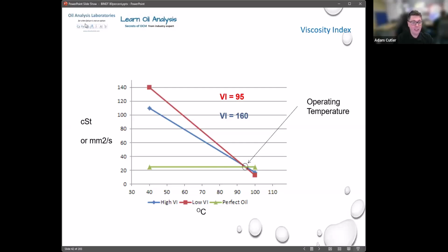But if we're coming into colder months now, as we're getting to freezing or below, it gets thicker and thicker and it's going off screen in terms of viscosity. So that'll take a lot of energy to start up in the morning, or it's very, very thick and gooey. Or you can have an oil that just doesn't go as thin as fast. So rather than having the one that's up here, you can have the one that's over here, in the extrapolation of going backwards in temperature.